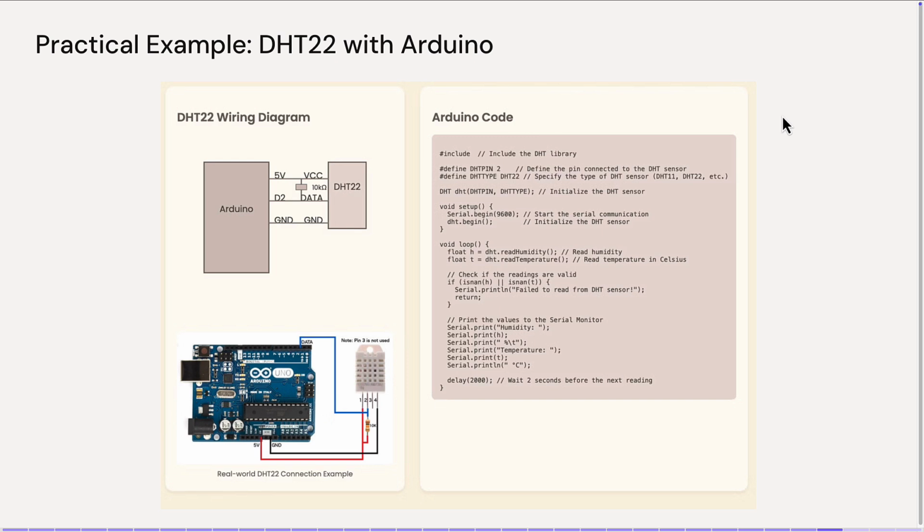So here, this is not complete. In principle, I include DHT.h, the library. And then we have a function. We define a DHT object connected to these pins, the pin for the humidity. And then we can use read humidity and read temperature. So there is a library that provides us these high-level functions. And finally, you can print it and see this in the console.